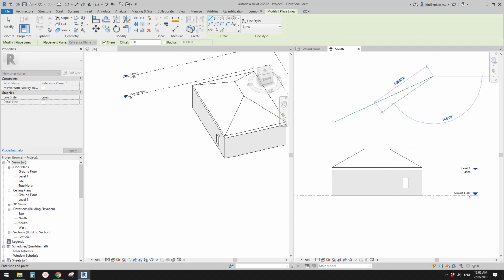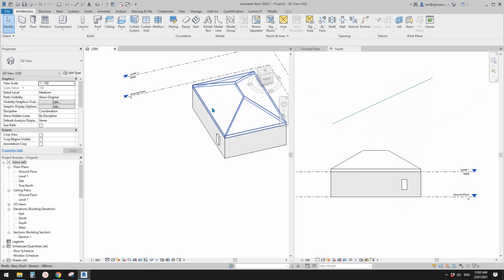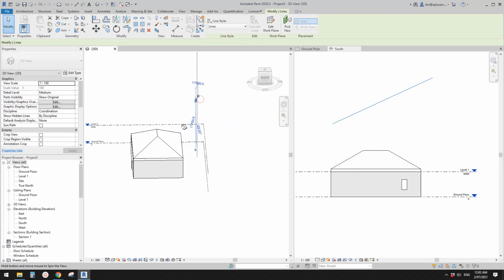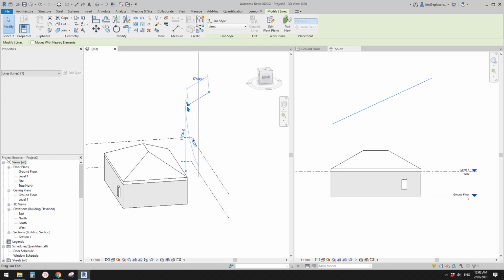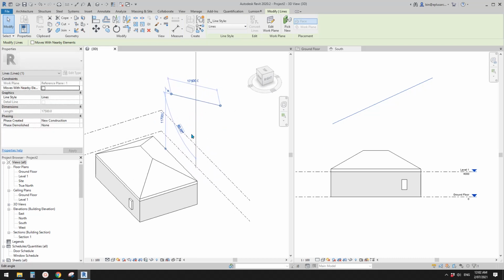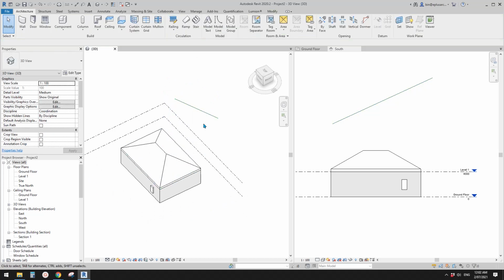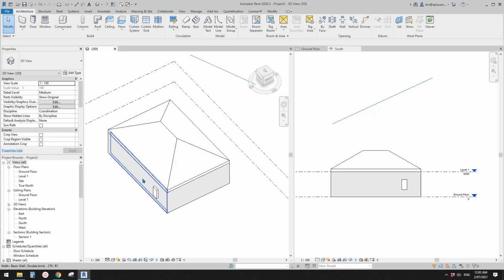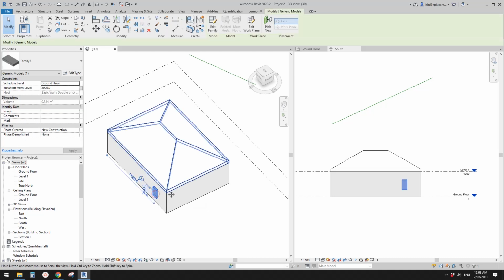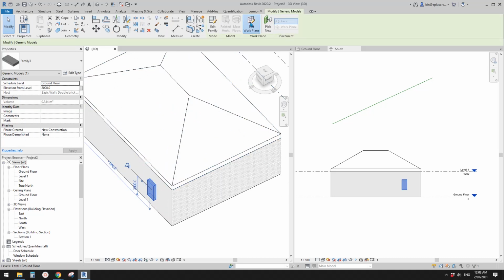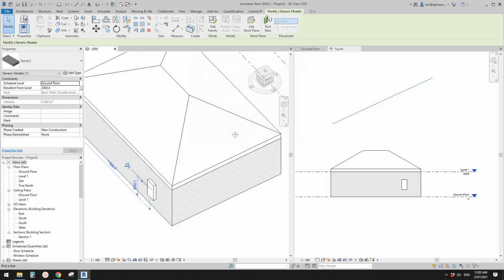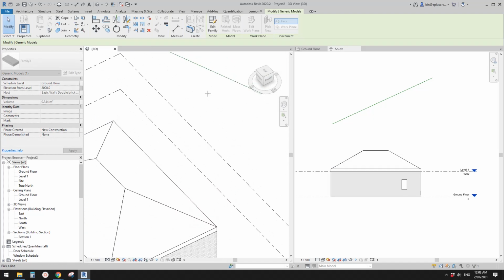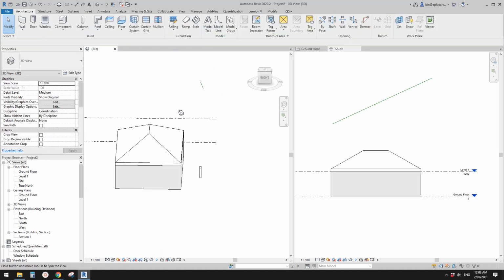This is a model line, and let's go to 3D view. You will see this model line. It was drawn in a work plan which is parallel to this wall. So let's try that. Select this family, edit work plan, let's try this one and OK, and see if we can pick this line. Yes, okay.